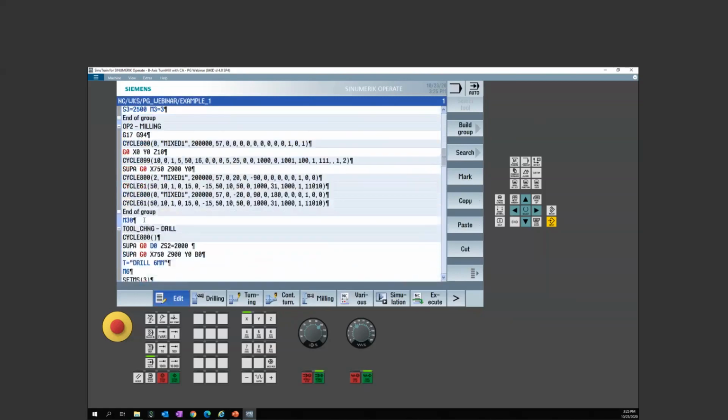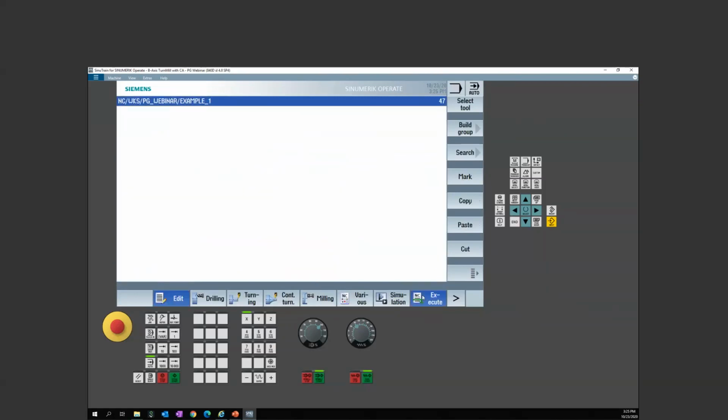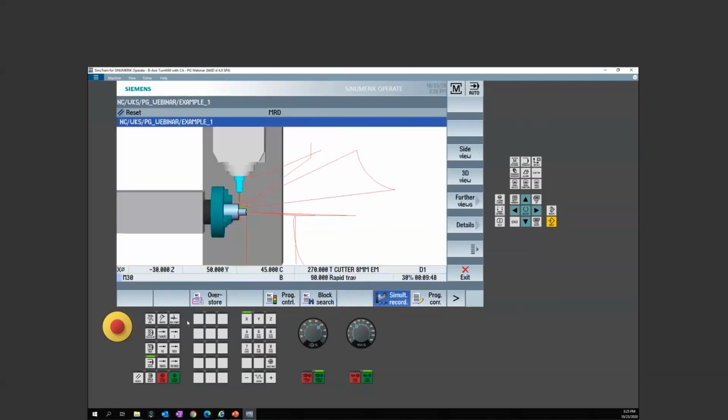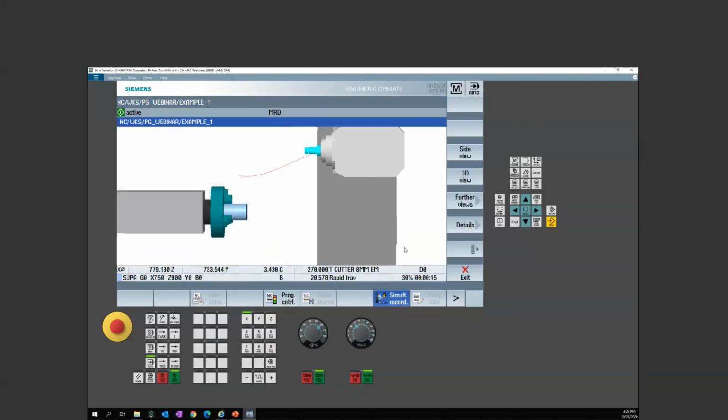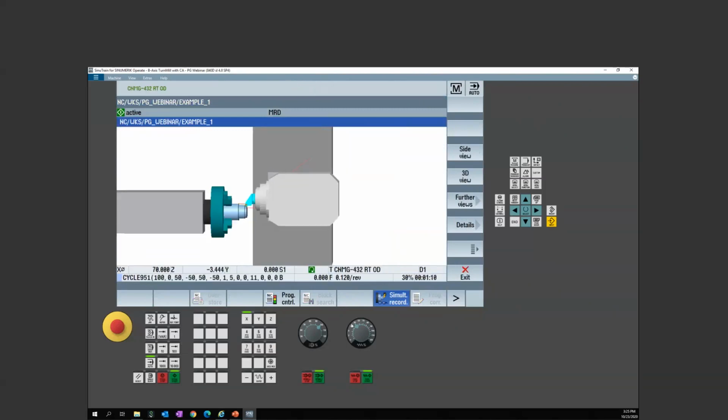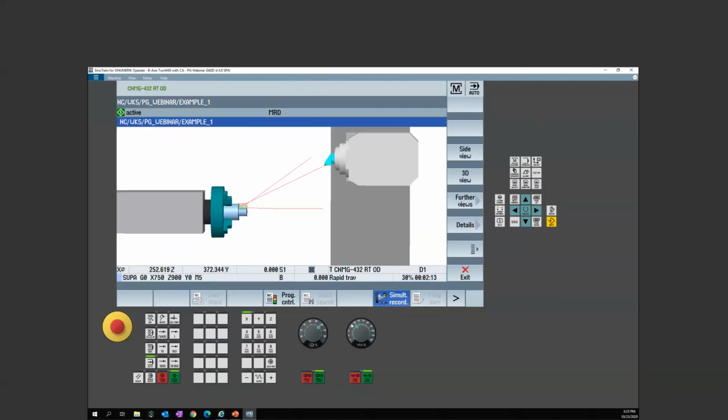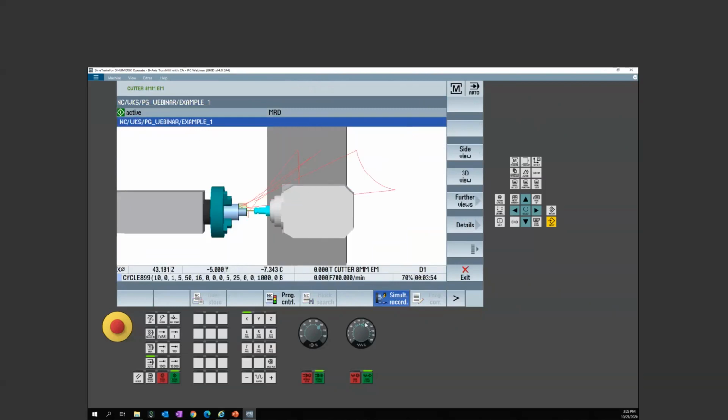No problem. I do this a lot, just kind of staging my M30 as I go. If I'm sent a program from a customer, and I don't want to try to look at the whole thing in one shot, I'll just slowly work my M30 down. The only thing you might have to add is maybe a safety retract or something at times, but it's just a nice quick way to kind of work your way down through a part program.